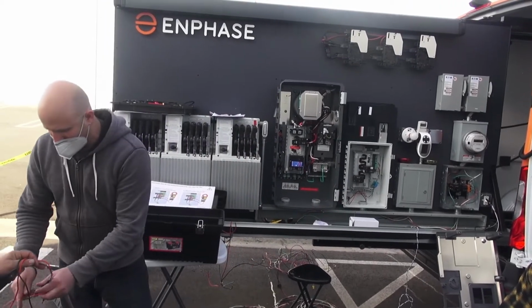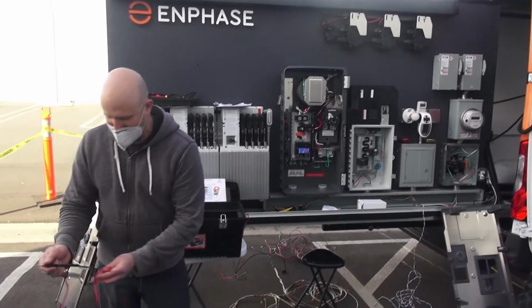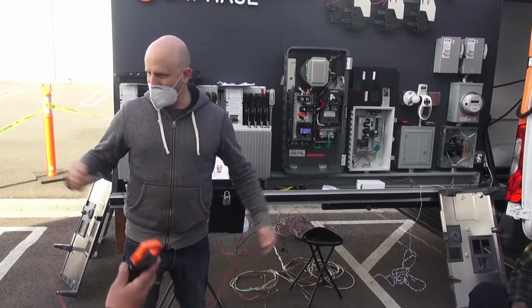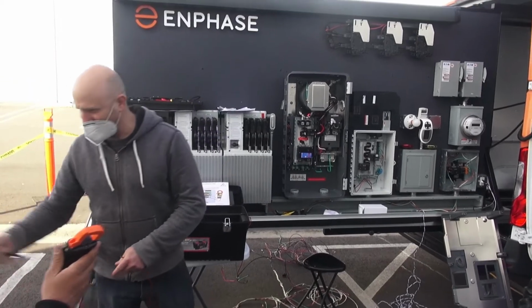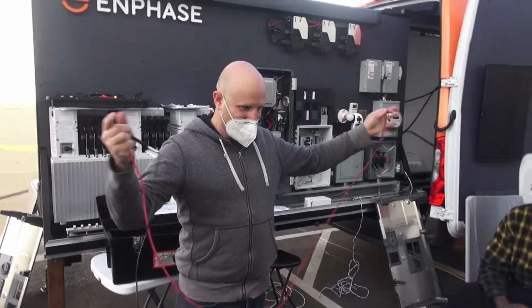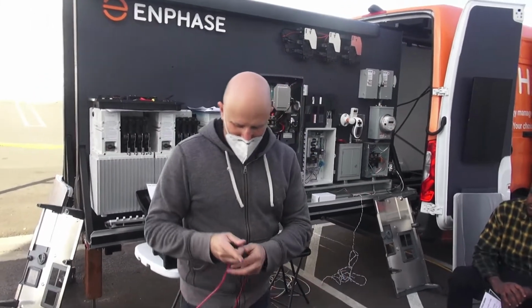If I measure with my meter from here to here, not here to there, not there, what voltage will I get? He knows where I'm going with this. 0, right? Because it's the same electrical line, same circuit. Now, if I measure...